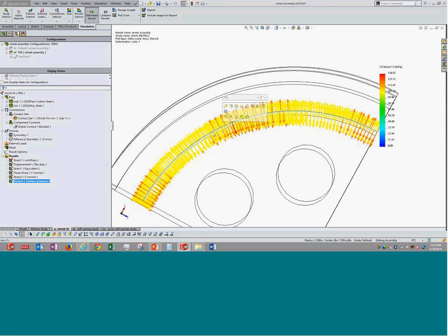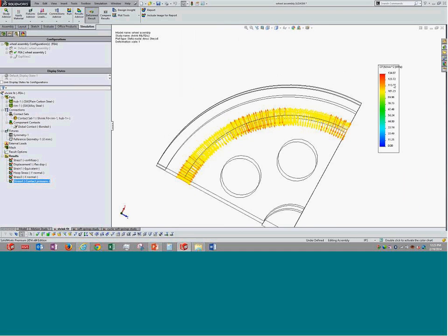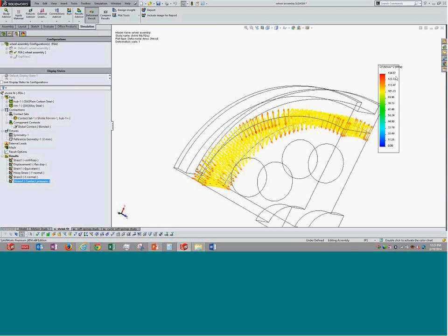Can simulation calculate the shrink fit force required? Now, what you might be wanting to say is that if one part, that is a shaft, is being pushed into a bearing or something, you have to find out how much force is required to push this particular part into the other part. One aspect is the contact pressure, that will definitely give an idea on how much force is required.